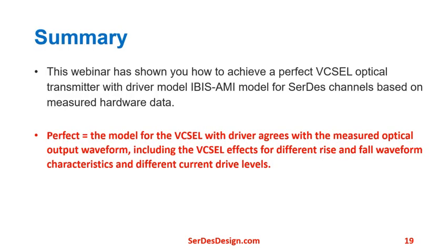So here's a summary. This webinar has shown you how to achieve a perfect VCSEL optical transmitter with driver model in an IBIS-AMI model for SerDes channels based on measured hardware data, where perfect means that the model for the VCSEL with driver agrees with the measured optical output waveform, including VCSEL effects for different rise and fall waveform characteristics at different current drive levels.